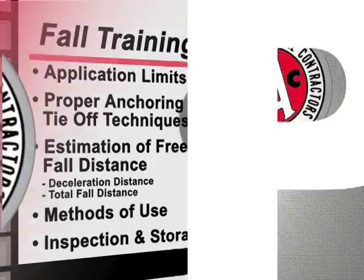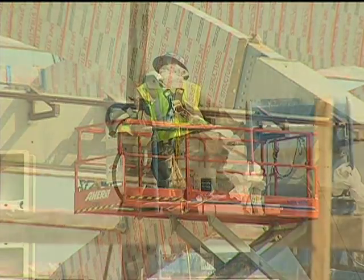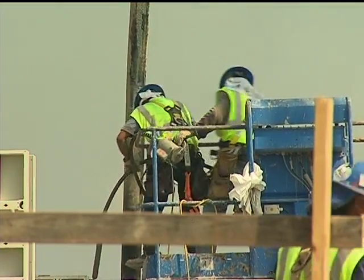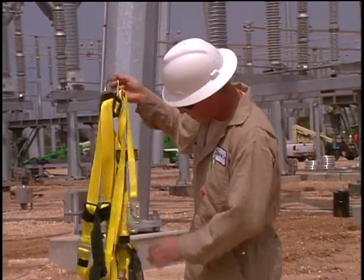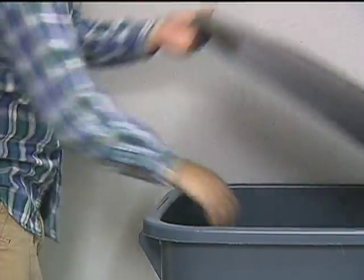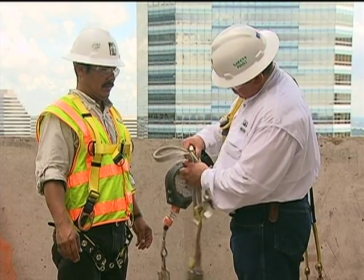Always use safe work practices when wearing a personal fall arrest system. Remember, careless or improper use can result in serious injury or death. Inspect fall protection equipment before use. Remove defective equipment from service. Replace personal fall arrest systems after a fall, or if they show signs of wear that could affect performance.